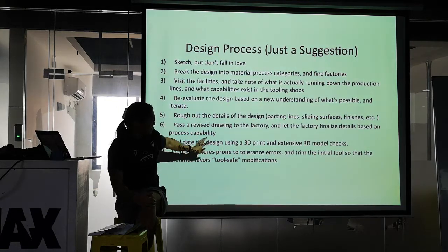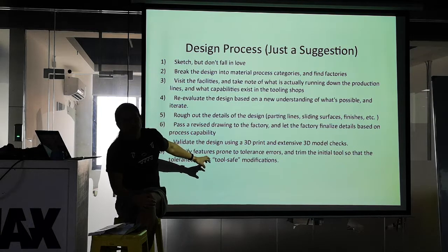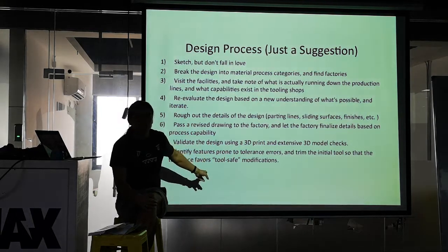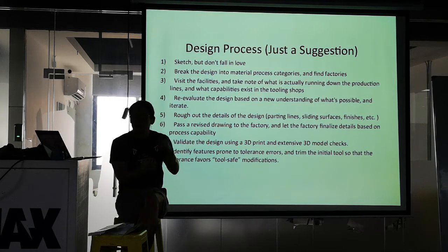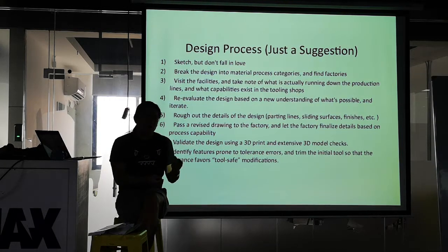And then finally, if you're going to tooling for plastics, consider what are tool safe modifications? As I was saying, it's easy to remove steel, add plastic. Very hard to go the other way around.